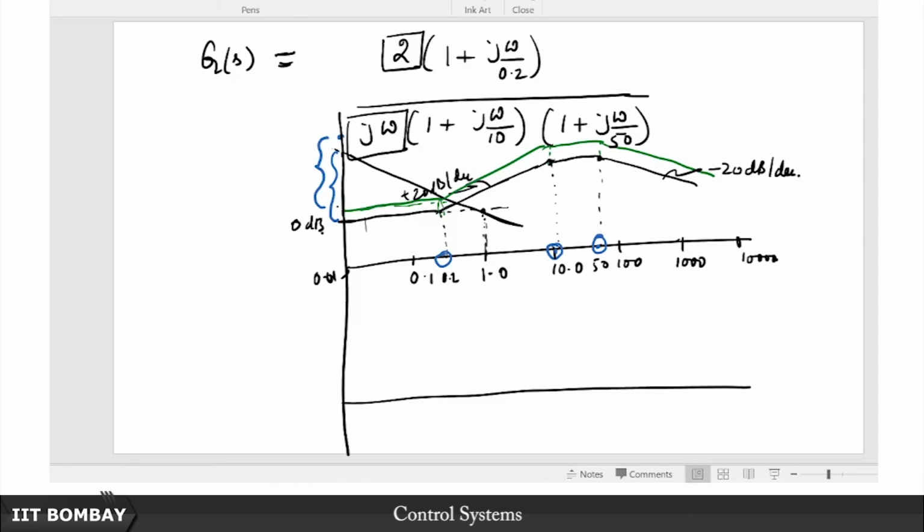So wherever you have drawn this y axis, think of its intercept, the y intercept, and from wherever you have this low frequency asymptote, raise the level by that. If this intercept is equal to, let us say, L, then this is now L plus 6 dB, that is the point here. Why 6 dB? Because I know that 20 log 2 is 6. So whatever was the constant value, you take 20 times log of that and add that to L. That is it.